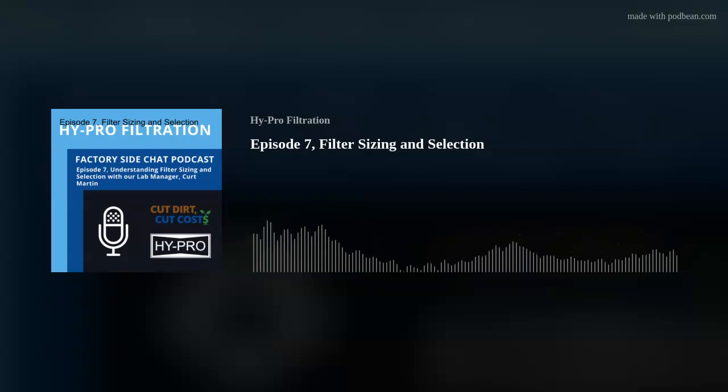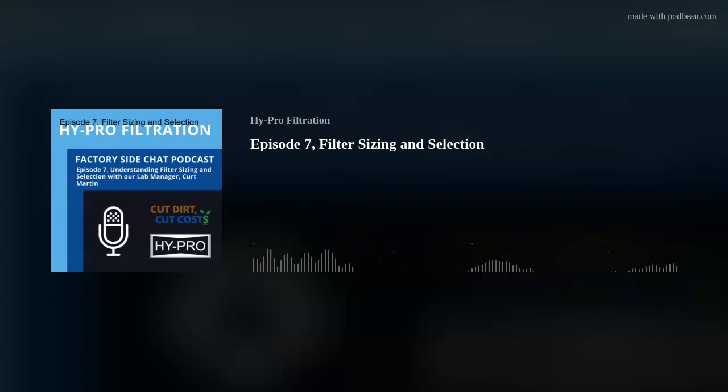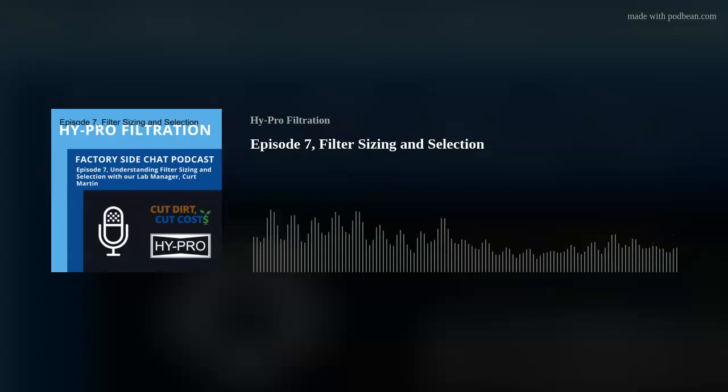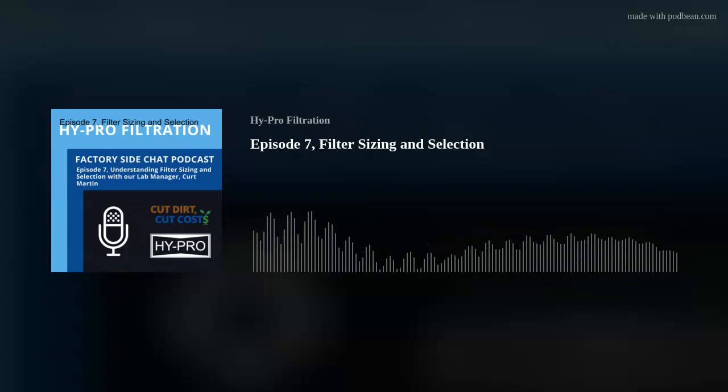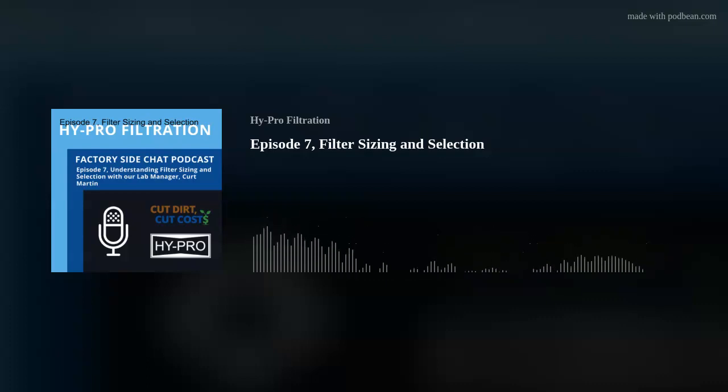That's good information. I think that's really critical because, just like you said, inside a building, a 500 gallon reservoir, a hydraulic power unit versus outside in a dusty environment, we are going to recommend a different flow rate for that fixed skid or that filter cart, and then that will dictate the filter housing size as well, because we want to make sure that we can keep up with the ingression and the generation of particles.